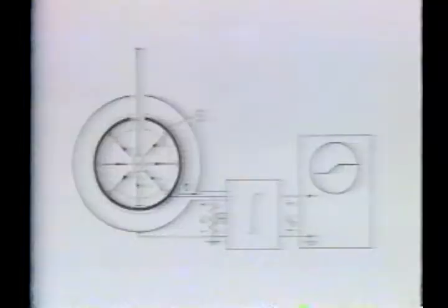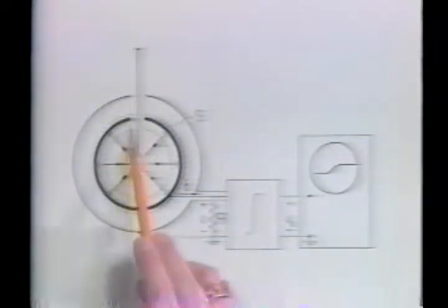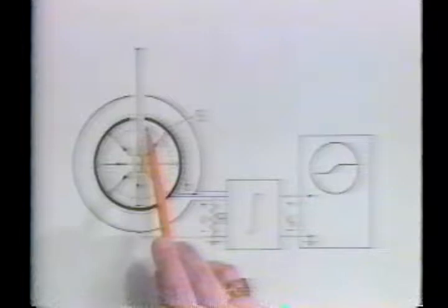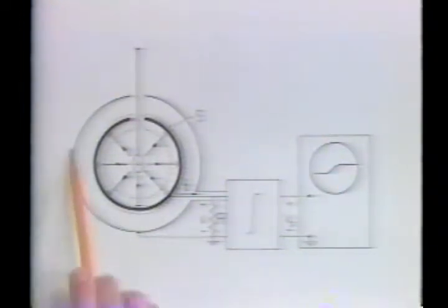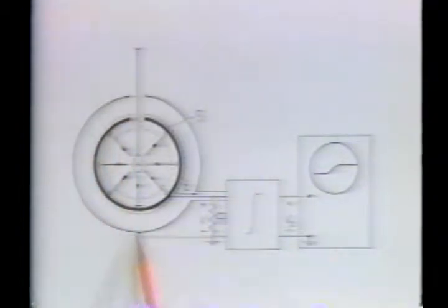By making this metal enclosure, which is called a Faraday cage, insulated from a surrounding grounded shield and itself connected to ground through the low impedance of an integrator. The shield is necessary to prevent field lines from outside charges terminating on the cage, such as from Professor Zahn's having walked on the carpet.